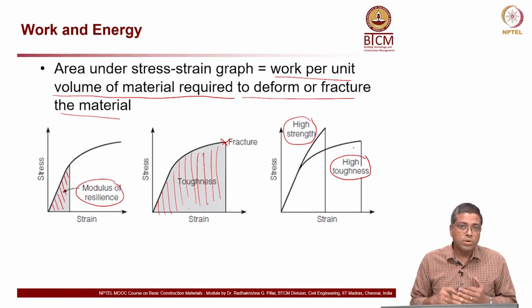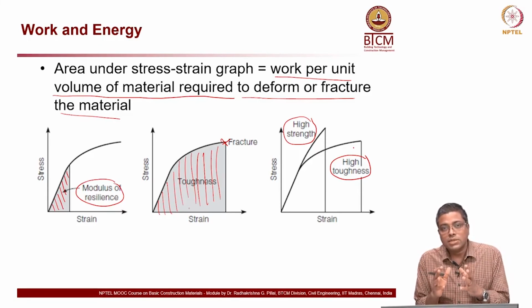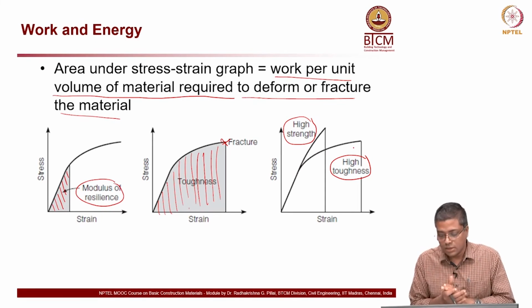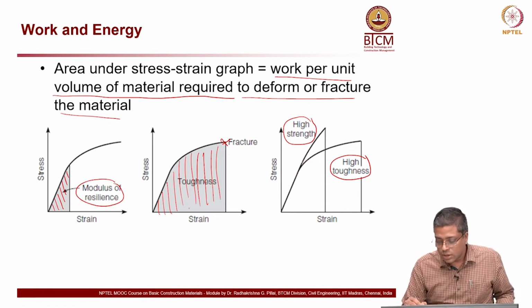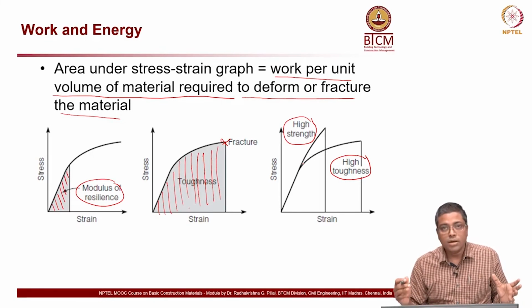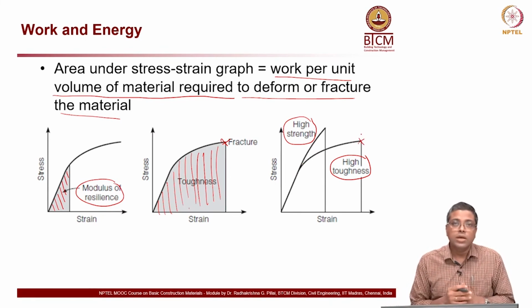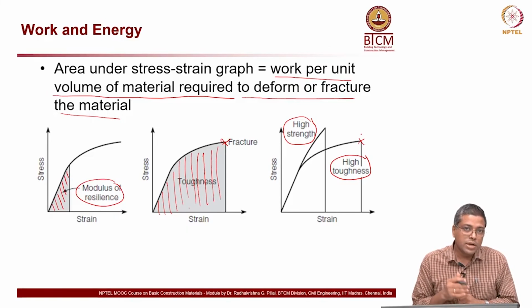Now, if you want to delay that collapse, because the collapse is essentially a function of the energy absorbed, sometimes, like the case we discussed about earthquake resistant designs, you have to have systems with high toughness, so that it does not break into two pieces until a lot of energy is absorbed. That's the case where we look for high toughness but not necessarily high strength material.